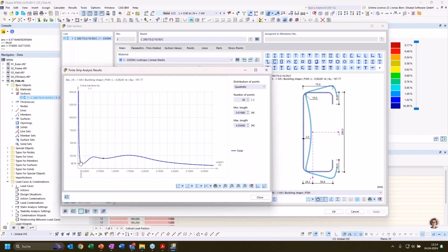So we can see that in the start, we have a very small member length. In this case, for example, the first minimum is evaluated for a member length of 14 centimeters, which would be the smallest column stub that we have just investigated with our shell model.